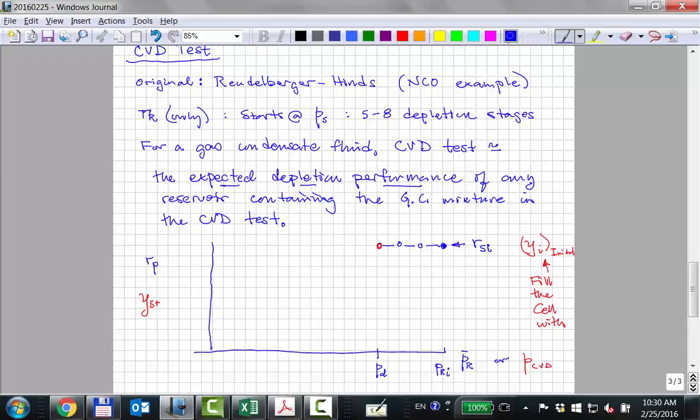Now, as the average reservoir pressure drops below the dew point, liquid will condense out. Okay? Just as you take hot air and you touch it to a cold surface, you condense out drops of water, right? In this case, you drop below the dew point pressure and you get liquid drops coming out of the gas, sticks to the rock, doesn't flow.